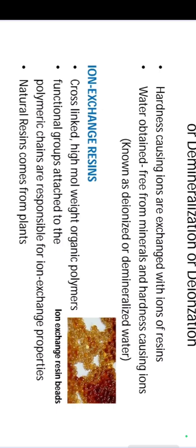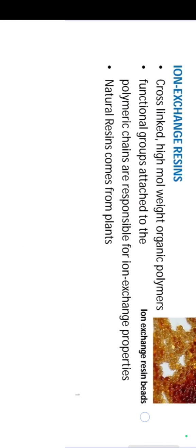It is one of the important points. The demineralized water does not contain anions and cations; only hard water contains the anions and cations. Thus, soft water is not demineralized water, whereas demineralized water is soft water.